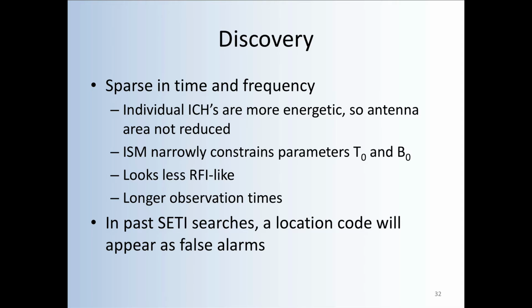Well, the first observation I would make is that the signal is sparse in time and frequency. That is, we expect little bundles of energy coming up at different times and different frequencies. And most times there's no energy, and at most frequencies there's no energy. But the instances of energy in the signal are isolated in both time and frequency. In order to make this reliable communication, the individual bundles of energy have to actually be more energetic to deal with this false alarm